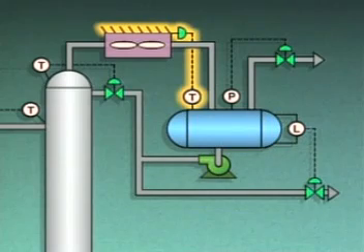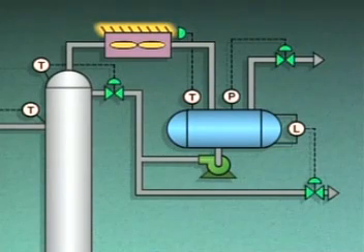The condenser temperature control loop senses the increase in temperature in the receiver. This control loop then adjusts the louvers in the path of the forced air from the fans in the condenser to cool the increased amount of vapors.